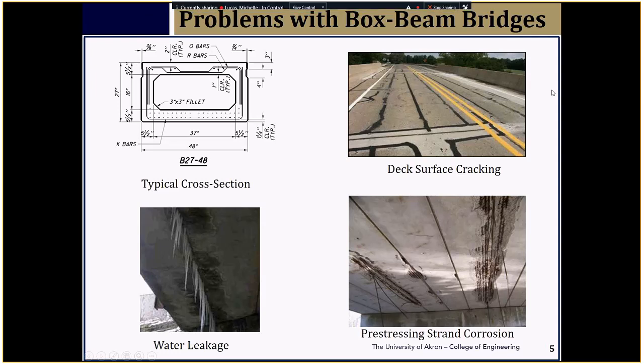So what we have is an opening at the top. If the box beams are placed side by side and the alignment is perfect, then theoretically it should give us a 3/4 inch recess to place the grout in. That's the way it should be, or it could be.